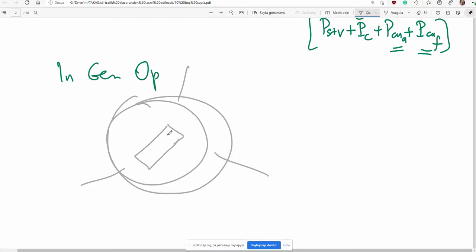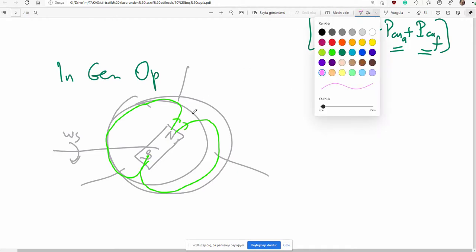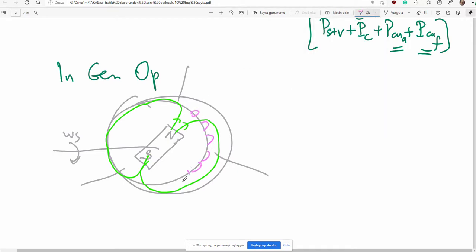Just imagine here's a simple magnet rotating, and then that magnetic field rotates at a certain speed, and then that magnetic field coming from the pole cuts armature coils somewhere here located in stator slots, and then there is some three-phase AC winding.